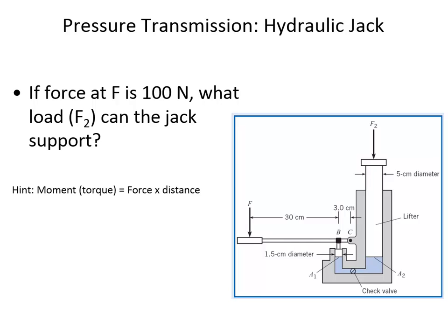And if it was something on there that's not quite so heavy, let's say that it's trying to lift something that isn't that heavy, well, that just means that then you wouldn't have to push that hard. You wouldn't have to push 100 newtons to get the jack to go up. This is a pretty exciting example, right? To understand how force is magnified, not only by leverage, but also something as simple as changing the areas.